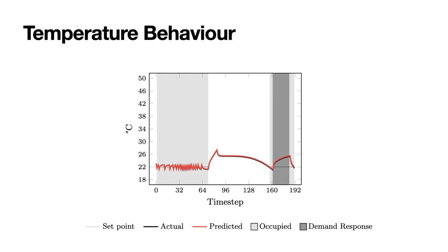We use a set point of 22 degrees. This means that it optimizes for the buildings to be near 22 degrees when the occupants are inside. You can see from the plot that the model optimizes for comfort in the morning period, and then it turns off the air conditioning when no one is inside during the middle of the day, and then it turns it back on before the occupants return in the afternoon. But in the afternoon period, there is not enough power to run the air conditioning system, so the temperature increases while the occupants are inside.